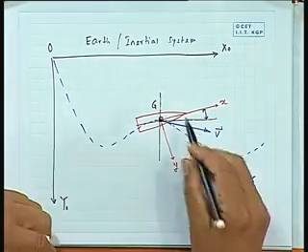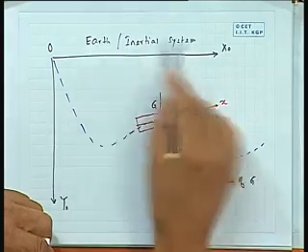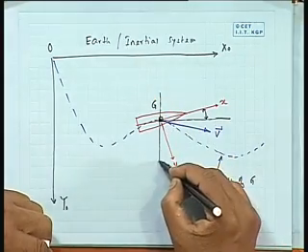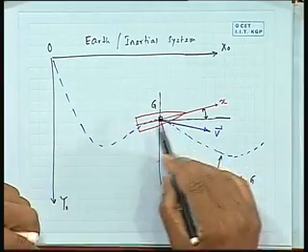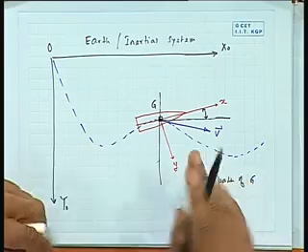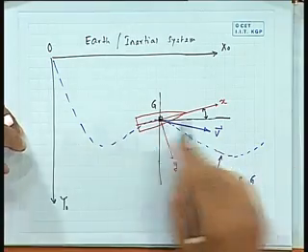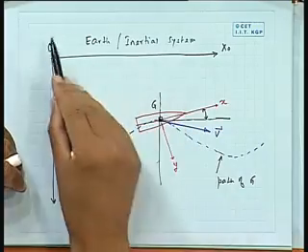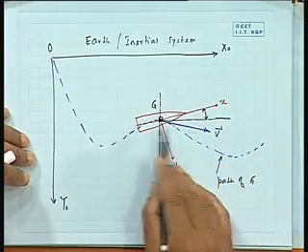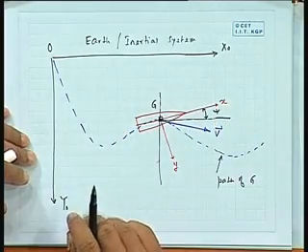First of all, I can draw another line here which is parallel to this x0 y0, that is a black line. This line is just parallel to that. So, now I have defined an axis system xy on the body. So, Gxy is fixed on the body. Gx is the longitudinal axis, Gy is your starboard side. Okay, standard fixed. When you are sitting here, you are seeing x is your bow and y is on the side. That is what you see. This is my reference line fixed on the globe. So, my heading angle is this angle, what it makes, that is what we call heading angle.